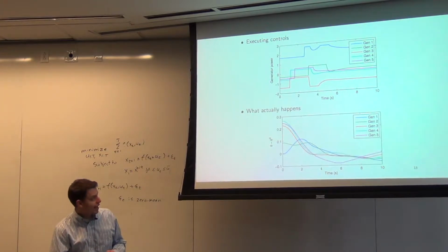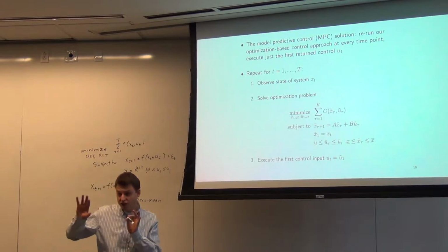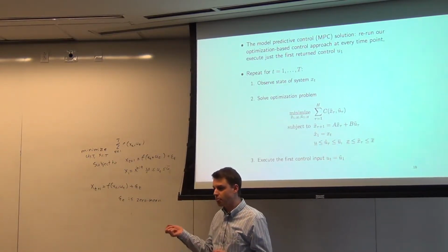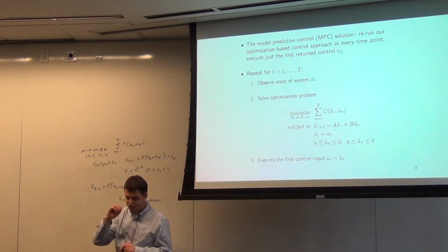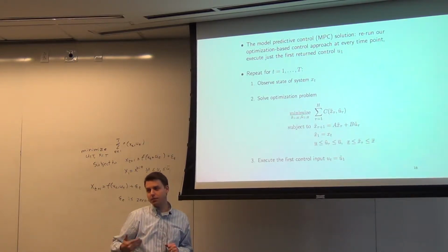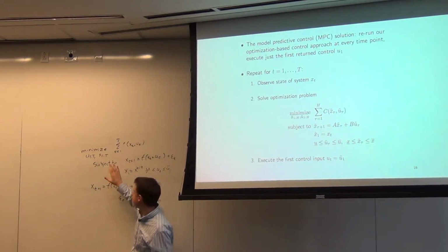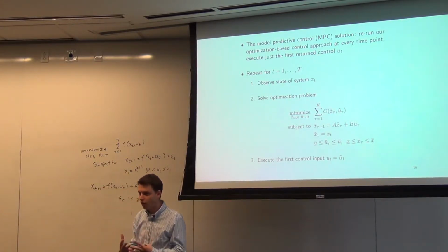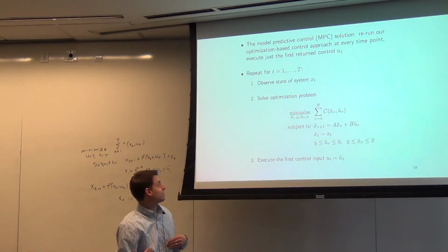And so to fix that, we take an obvious idea, and this is what MPC is. Instead of running optimization once at time 1 and then just taking those actions, at every time step we re-optimize this problem using the x init that we actually observe, rather than the one that we expect to happen if there's no noise in our dynamics.